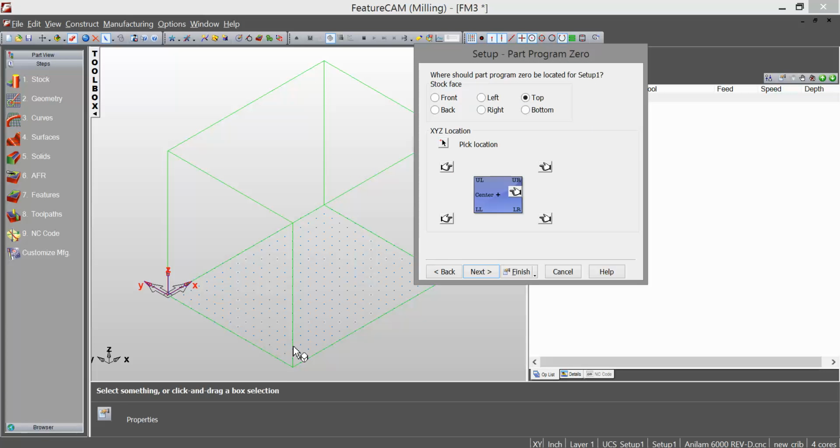Your X, Y, and Z have to be pointing in the same direction as they typically point. The positive X is going to the right, the positive Y is going above the block, and Z positive is going straight up. I found that if you try to use the bottom upper left hand corner, it does not put it in the right spot.